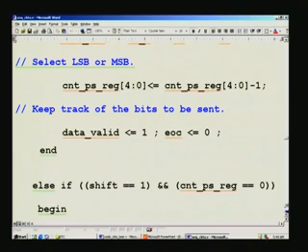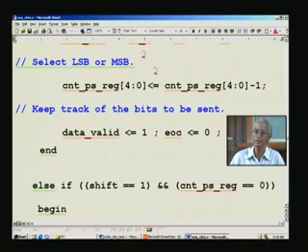end of conversion is deasserted because it is not the time for it. And on the other hand, if this condition is satisfied, that is when it has output all the 16 bits. So, each time it will go only through this path, and it keeps on outputting bit after bit after shifting, and when the counter touches 1 here, even then it will do this, because one more bit is to be processed. Next time it comes over, this condition will not be satisfied. A similar condition was there which was non-zero, and that condition will not be satisfied, therefore it will not reach this, and instead it will come to this and process from here.